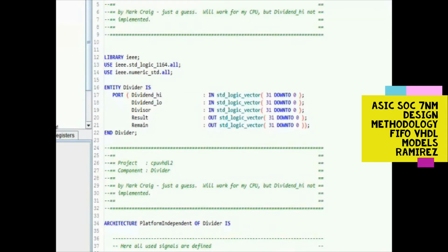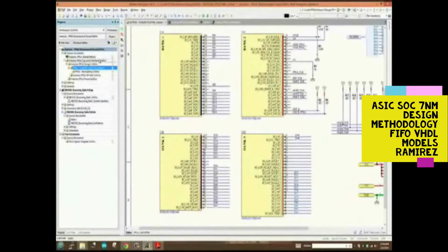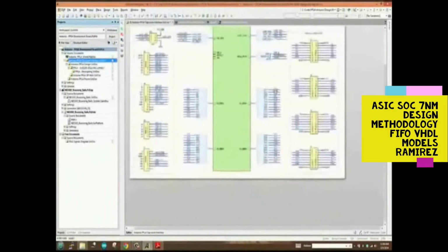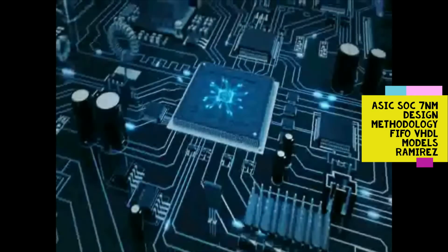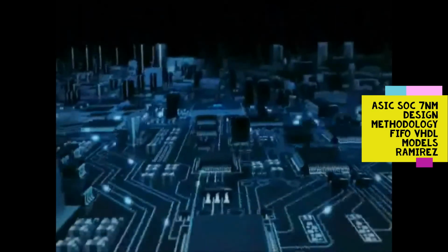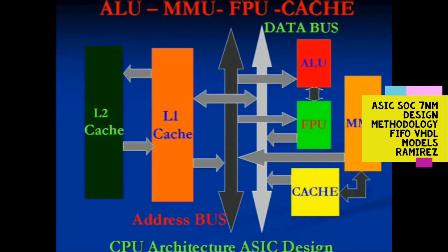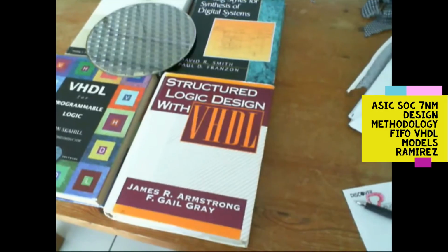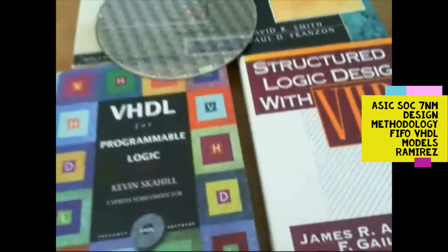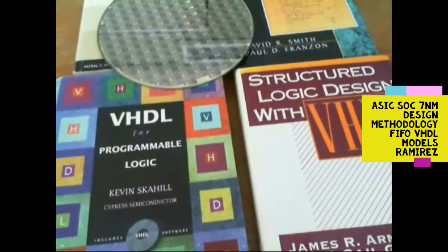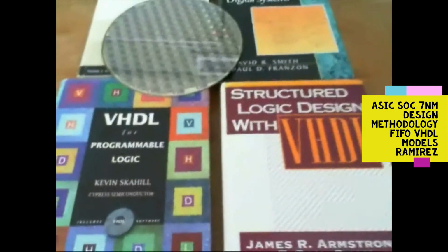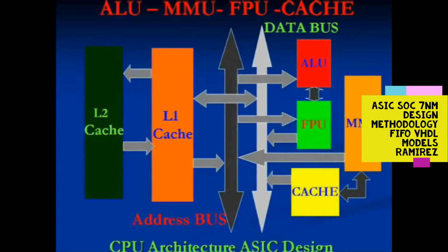Also, the layout process was completed. Here, the gate level netlist is converted to a complete physical geometric representation. The first step was to do floor planning, which is the process of placing the various blocks and the I/O pads across the chip area based on the design constraints.